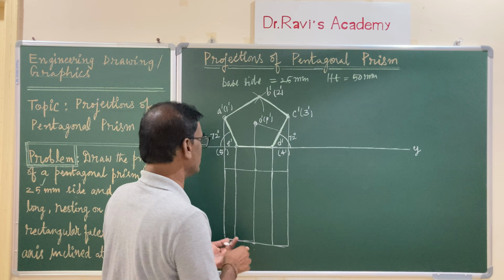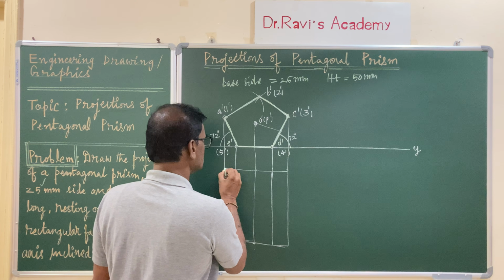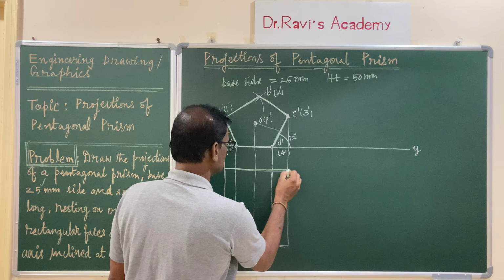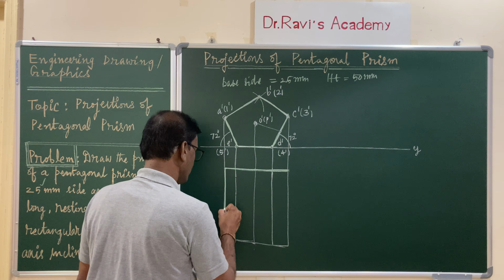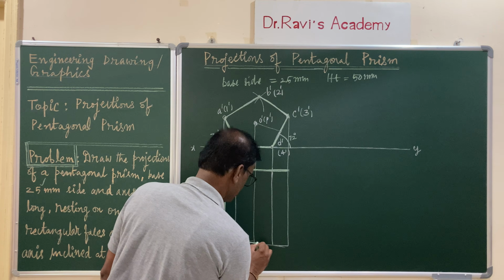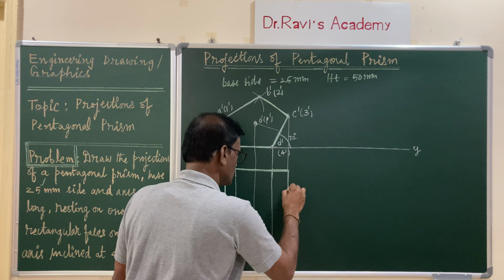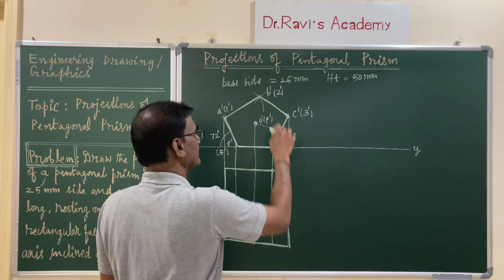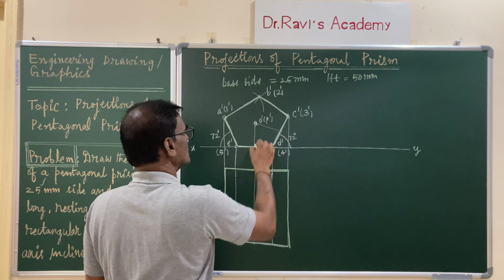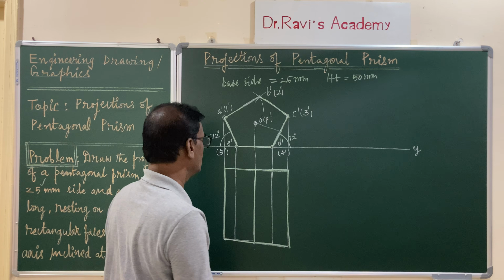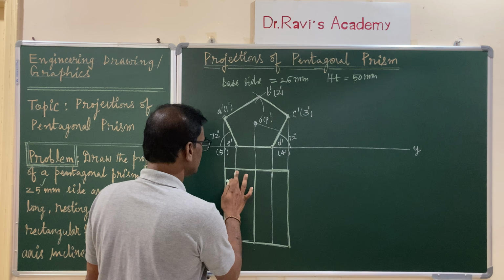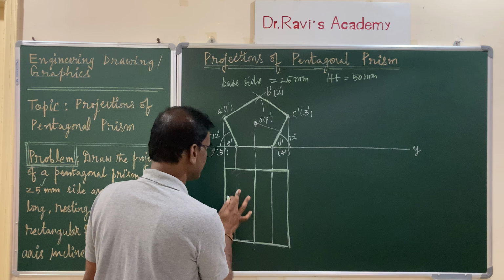First you join the borders of the solid with an HB pencil. So you make use of the HB pencil to draw the projection in the top view. And see that this is also HB pencil, it is passing over this. This is also a continuous line. And observe carefully here, this is a hidden edge.